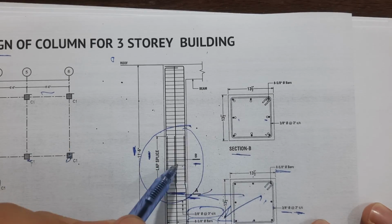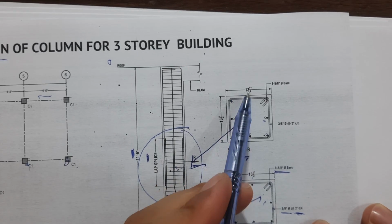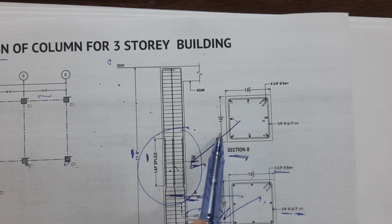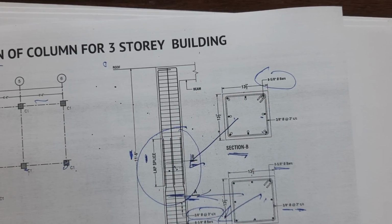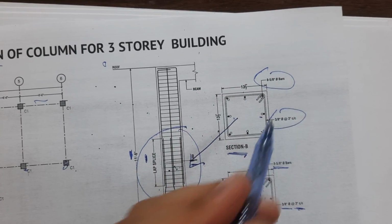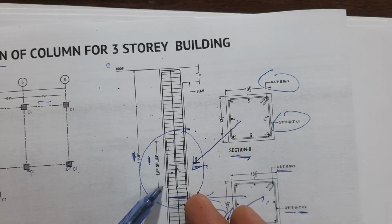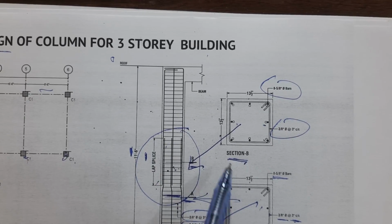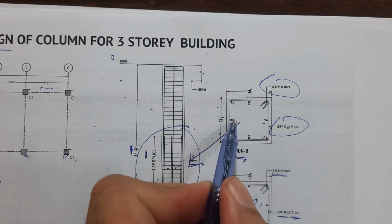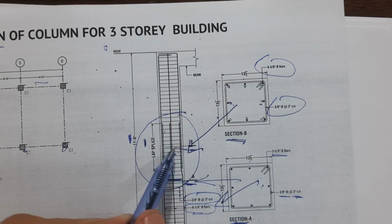Now we are discussing this place. So look here, section B. Section B is considered in this plan. The size is 13 by 13, 13.5 by 13.5 inches, with 8 steel rods, and the diameter is 16 millimeter. The same applies to the lateral ties details, the spacing at the lapping or splice length place, or after the splice length, without splice length. So these are the details, guys. You can see the other steel rods are connected with this, which shows you the lapping length.